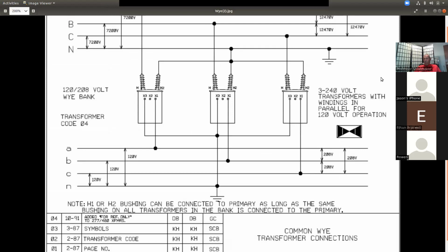Open delta, three-phase. A lot of three-phase or just a little three-phase and a lot of single-phase? Think of the restaurant. Only one three-phase air conditioner, right? Right. So open delta has a little bit of three-phase and a good bit of single-phase. Closed delta, where do we use it at? A lot of three-phase, a lot of motor activity going on out there.